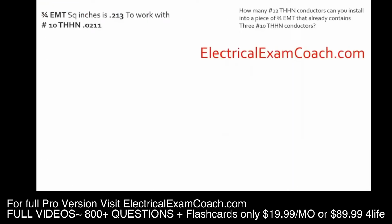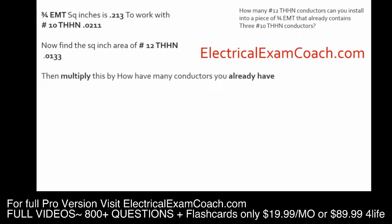Now that we have our conduit and our starting conductor, let's go ahead and write down our number 12s. That's the conductor that we want to install. Then we'll be done with the code book, and all we have to do is some simple math. After we find that value and write it down, we can proceed. We multiply our conductors that we already have: 3 number 10s multiplied by the value for a number 10, and that gives us this number.